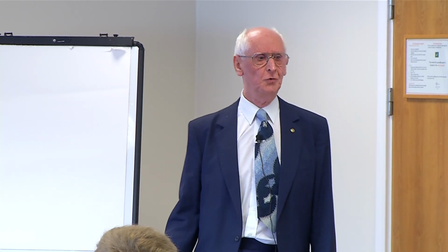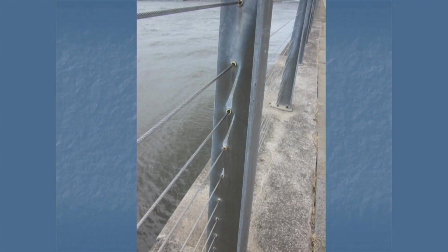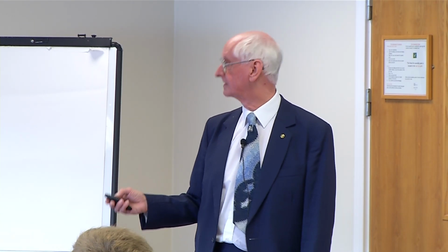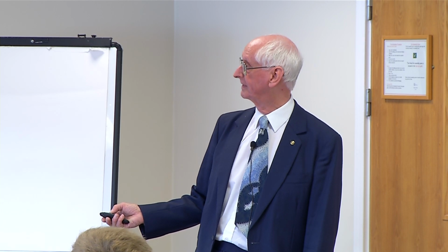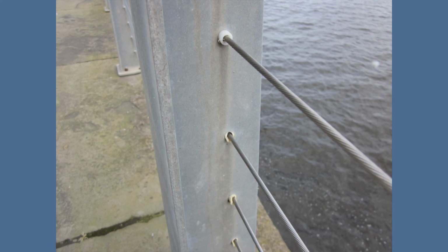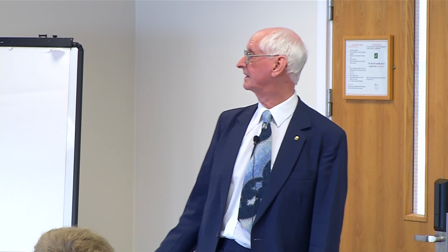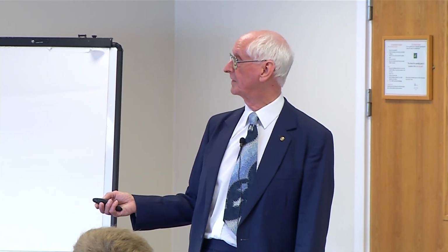And this was obviously a stormy day. I don't know how it managed to do this, but the corrosion cell is actually going upwards. So I can only assume that that was the result of a very severe storm at the time. And if you look at these, you can see this one is broken away completely, that one's broken away, that one's broken away, this one's yet to go. But the problem was there right at the design stage, mixing stainless steel and galvanized steel together. They also had a problem with all their fixings as well.